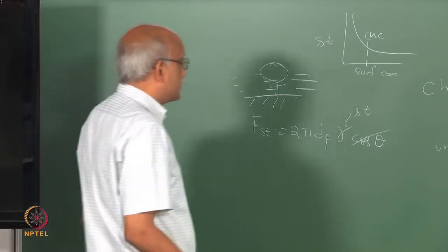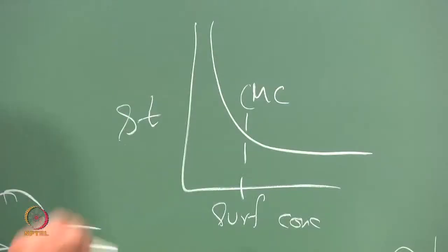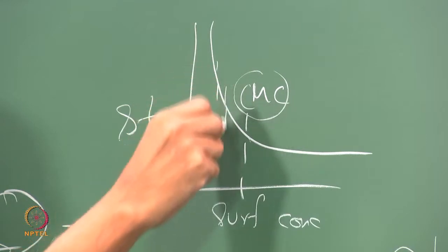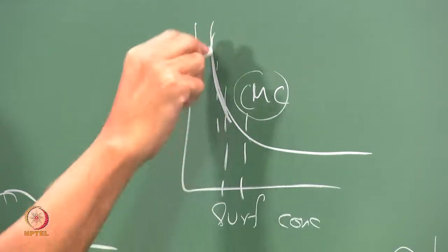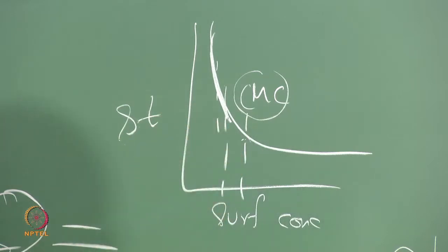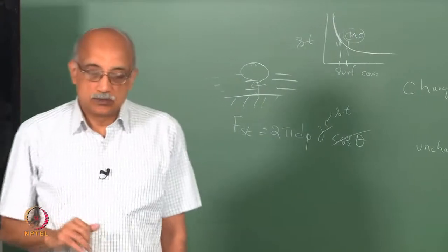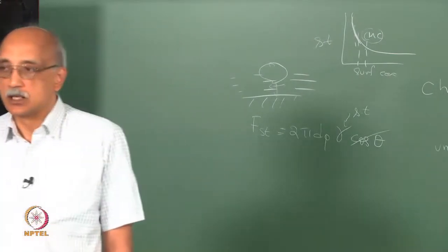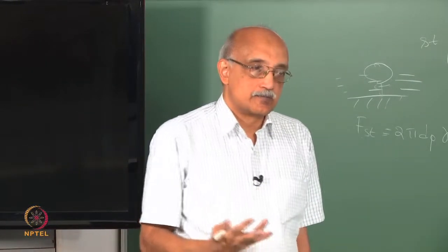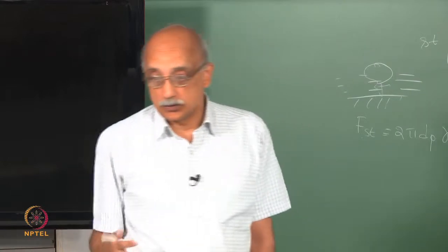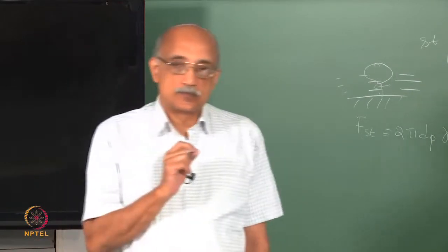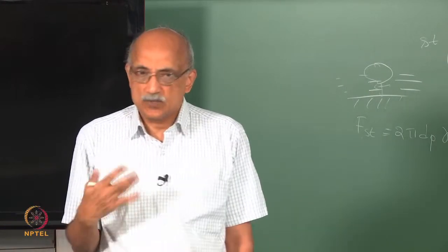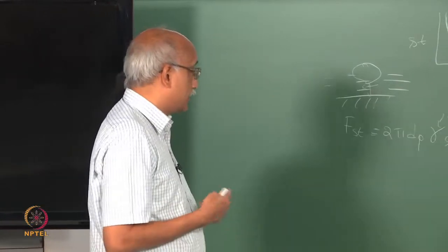So, typically people like to keep the surfactant concentration well below this critical micelle concentration value. Somewhere where there has been a steep drop in the surface tension, but you are not yet at the CMC value. There is no hard and fast rule that it should always be set at 75% of the CMC or something like that. It's something that you need to do by trial and error. For every system that you operate, for every process that you own, the ideal surfactant concentration / liquid surface tension may have a different value, and you have to learn that by experimentation and so on.